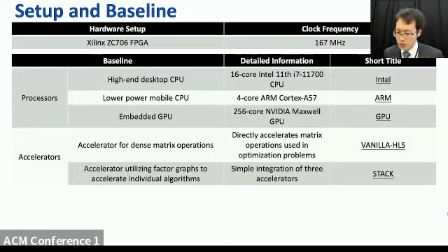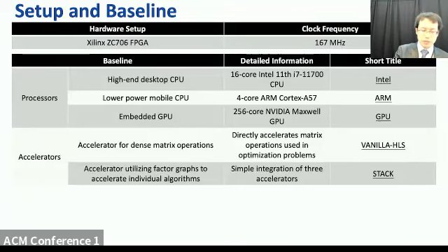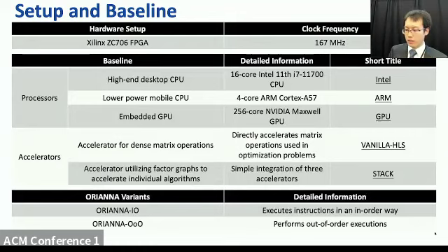So for the accelerators, the first accelerator is where we directly accelerate these matrix operations without considering any sparse structures, which we call the vanilla accelerator. And the second accelerator is where we design accelerators for each task and stack them together, which we call the stack here. And we provide two variations of ARANA. One is the in-order execution, and the other is out-of-order execution.